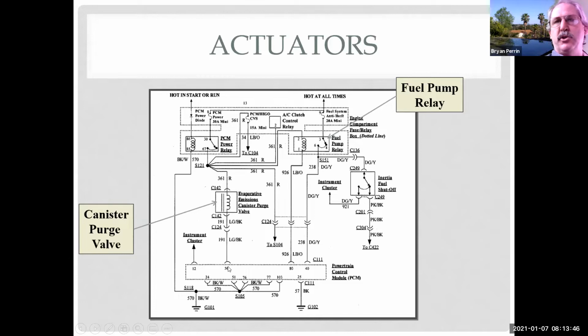So I'll see voltage here because I can only drop voltage through resistance if I have current flow. And we know we have no current flow in an open circuit. So as soon as we open it up, all I have is potential. So we'll see that system voltage all the way down to here. As soon as the transistor closes, now it's going to apply ground, and ground's going to come all the way up here to the load.